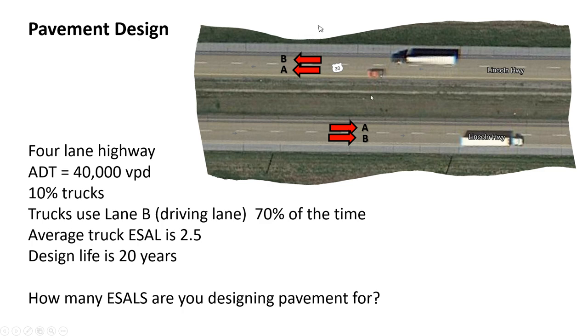If there's 3 lanes, sometimes the middle lane has actually got higher truck volume than the right lane, especially in a congested area like 294 and the tri-state going around Chicago. There's a fair number of trucks in the right lane, but more of them prefer the second lane through there. I think that's mostly 4 lanes in each direction, so that would probably be lane C. That tends to be where I see most of the trucks there. That would actually be your design lane